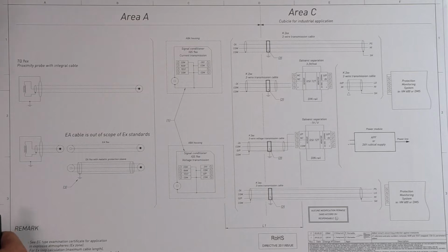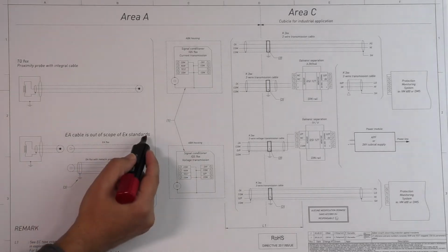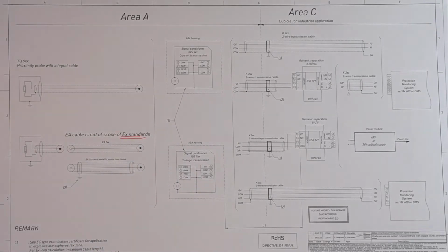We have the exclusive environmental standards that gives us also some rules that we must follow to be compliant with those standards. And then you have the general electromagnetic compliance standards that imposes also some rules to make sure that our system is not perturbing other systems in terms of emission, but also that it is immune or not susceptible to emission from other devices.